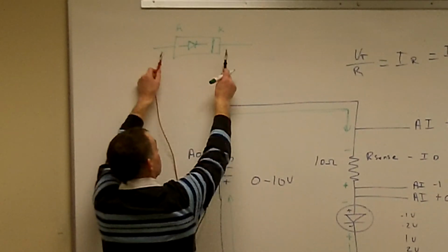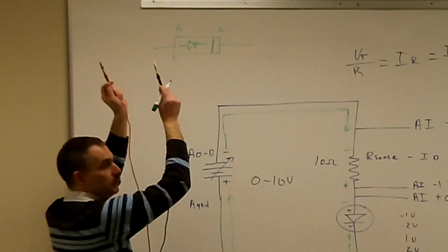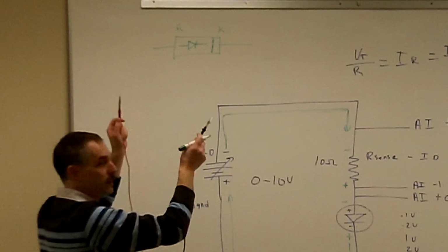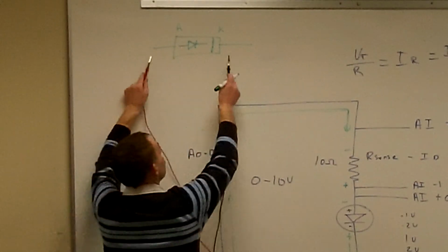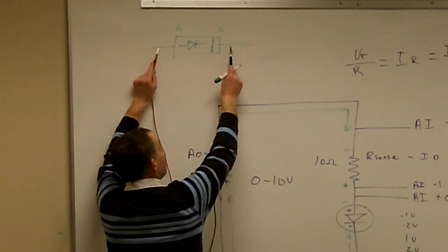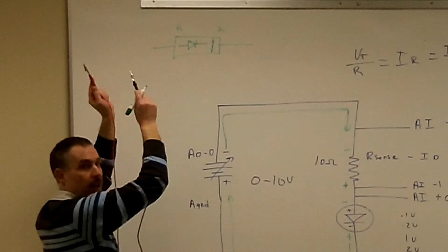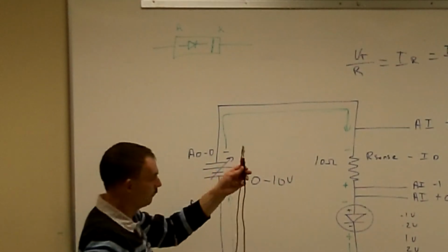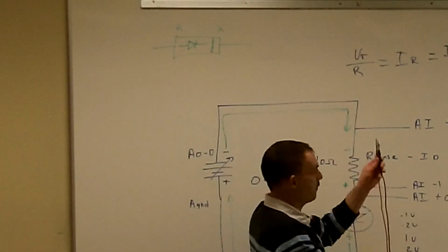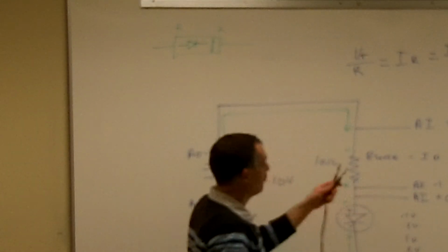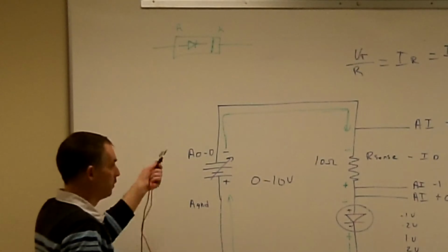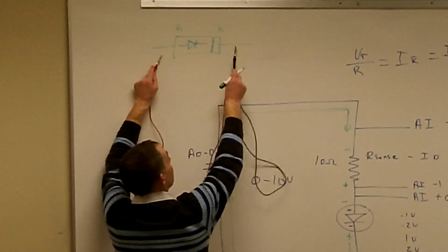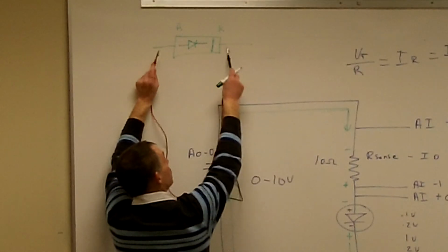And if that diode starts to conduct, it acts like a what? Open or a short? Short. A short. So I'm going to start seeing some resistance across there, depending on how big of a power supply you have in your ohm meter, because it all varies from power supply to power supply, from data acquisitions to whatever. It's going to depend on how much resistance it's going to measure.